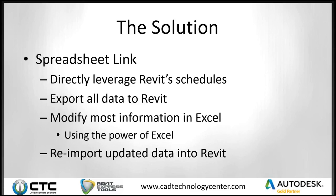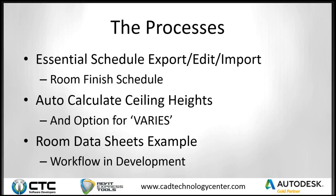And we're going to use this for 3 very explicit workflows today. We're going to use the essential schedule export, edit, import functionality that I just described for room finish schedules. We're also going to leverage this to automatically calculate ceiling heights, and we're going to add in the option that everybody's been asking for a while for, because that information often appears directly in my room finish schedules. It's usually entered by the interior designers or partially collaborated with the architects, but for the most part, I see a lot of the interior designers I collaborate with being the responsible party for entering this, and they have to go through and query a lot of that information manually. So I can try and pull some of it automatically, and show you how I do that today.